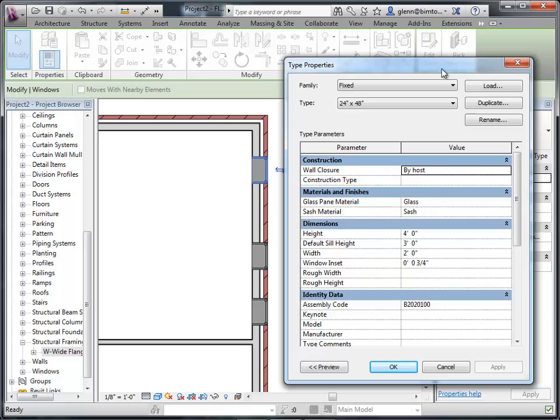With this fixed window right here, you might notice that the glass is currently way out towards the outer edge of the window right now. Okay, and that's a good way to do it. We can go ahead and have it only 3/4 of an inch of a recess and have a big sill on the inside. If you've been walking around looking at the Stanford buildings, though, you'll find that we actually do it almost the opposite way here. We tend to have very deep window sills on the outside, and the glass is recessed very far back in. Okay? And in the old stone walls, that seemed like an appropriate kind of construction. You can kind of choose just which way you want to do it.